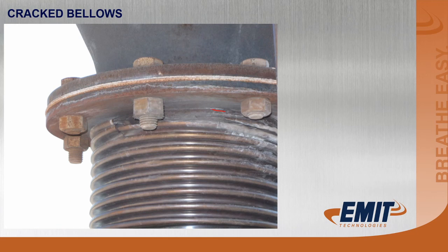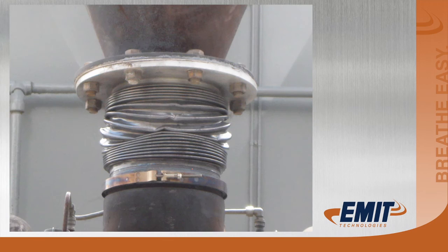Commonly, if you see ash on the outside of the exhaust, you know that there's a leak somewhere close by. You can see this crack travels all the way along in here. And when you start that engine up, that ash is washed out from the moisture from startup, and then it builds up on the outside of the pipe. It's an easy sign to spot a leak.